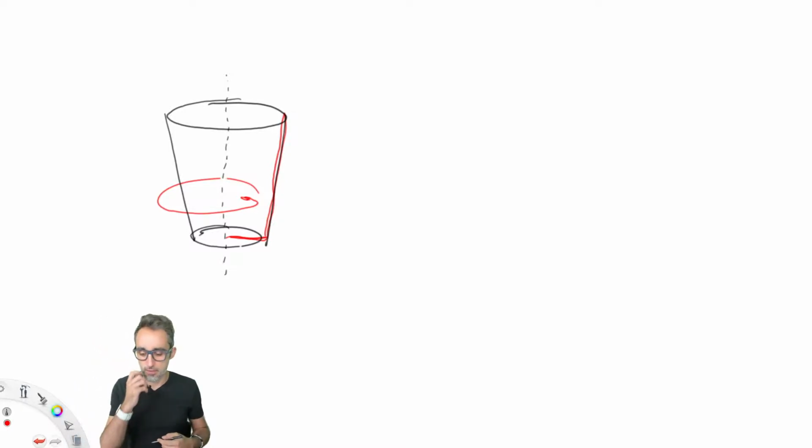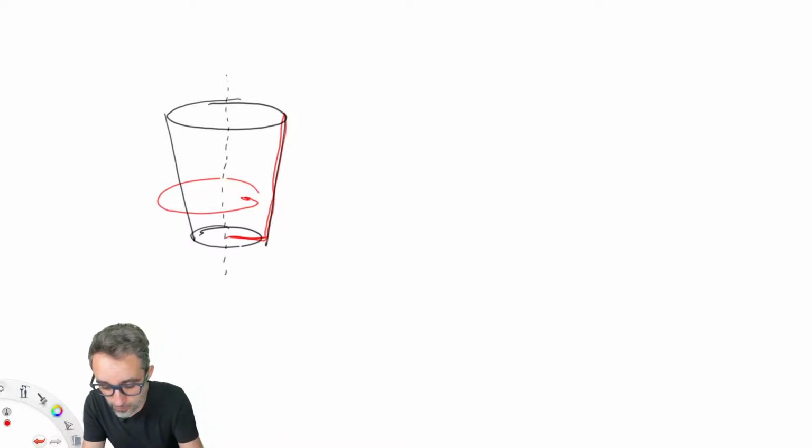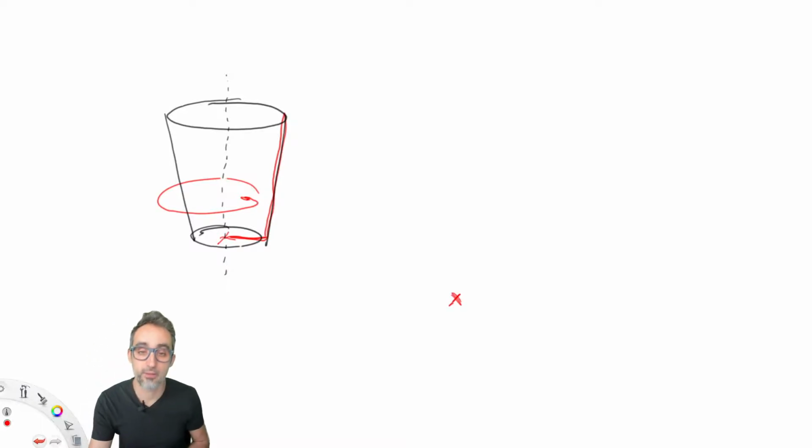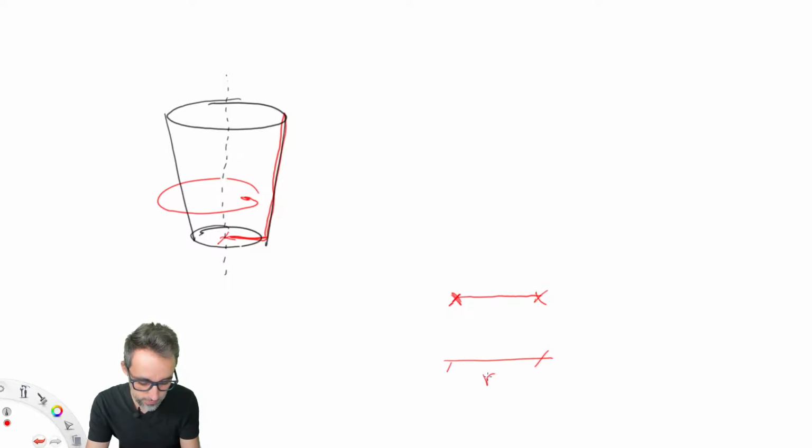So for example, first of all, probably the input that I want for this glass is going to be this point here. I want to start from the center of the glass, the center of the bottom. Then something that I will also want to have control over might be the radius of the base. So I may want to have control of this distance, and therefore there might be another point here, and this is going to be the radius of the base.